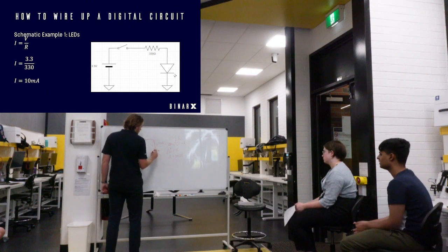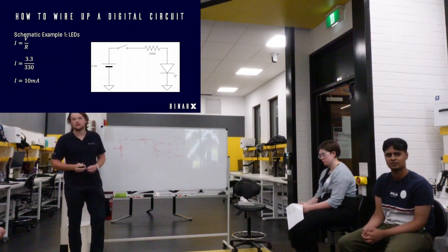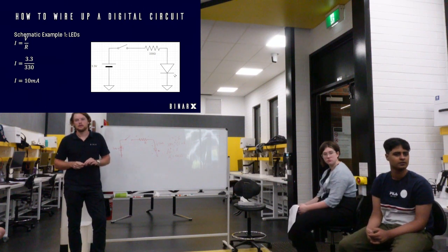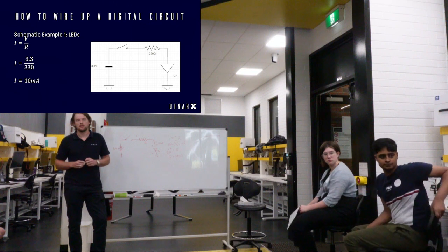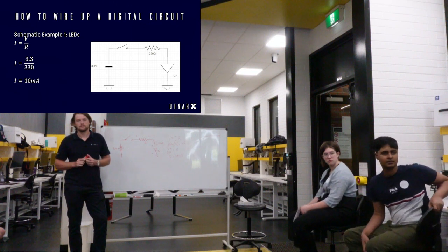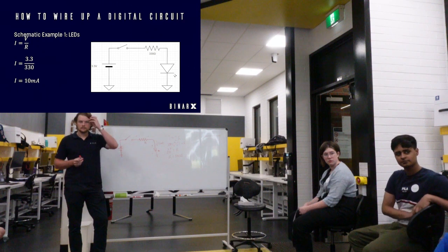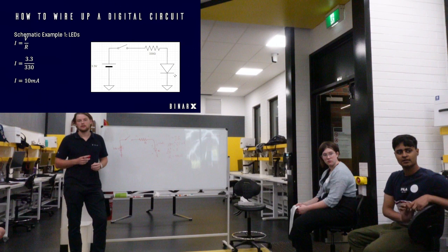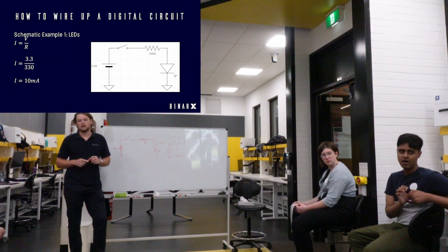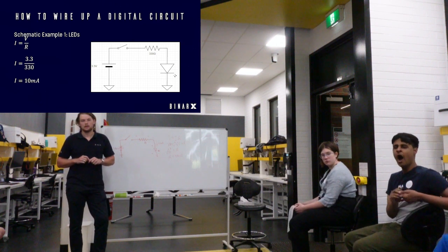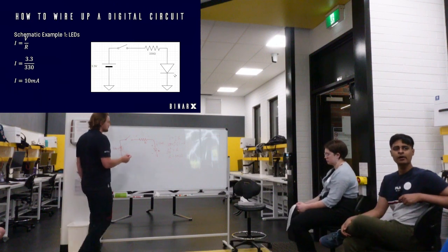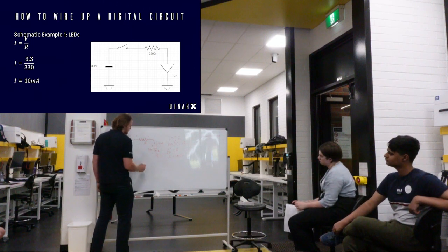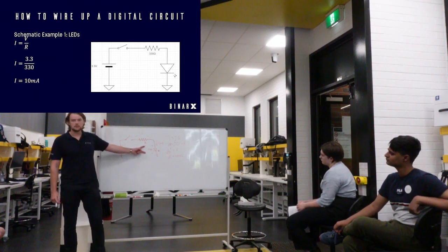Is that just taking into account the natural resistance in the LED? Yes, it's not technically resistance, but we call it the forward voltage drop. It's like, if you have 12 volt LEDs versus 24 volt power supplies, when I was working in signage, you could only run them a certain length because the wire would have a natural resistance. So you've got a maximum length of your Christmas lights if they're 12 volts, like 3 meters, and then it's double that for 24 volts. Most diodes normally have a 0.7 volt voltage drop, which essentially you can treat as a resistance in your circuit.